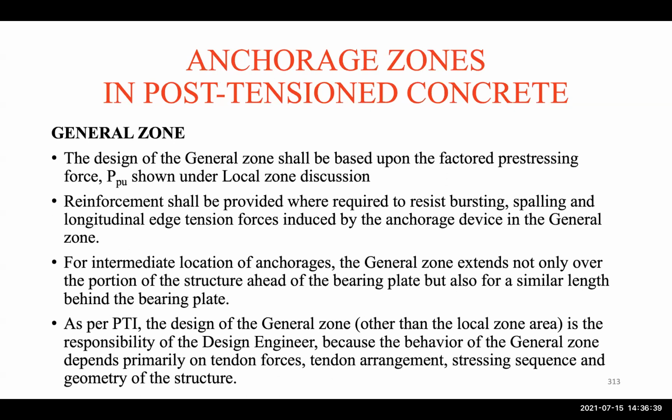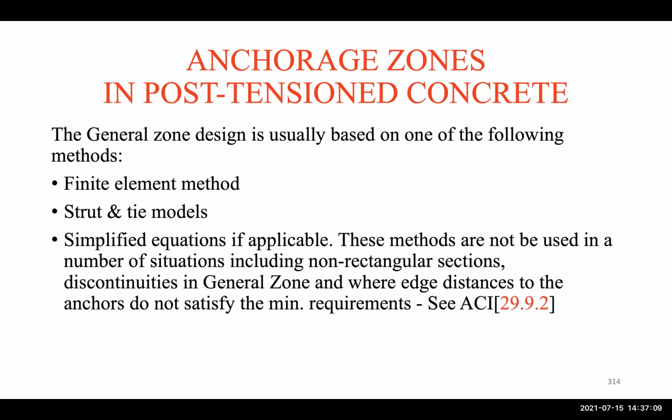According to the PTI, the design of the general zone is the responsibility of the design engineer. So this is something you have to design if you are designing the building. Sometimes, of course, the PT suppliers design that, at least how it used to be before. But now, with more use of PT, the engineer of record does that.